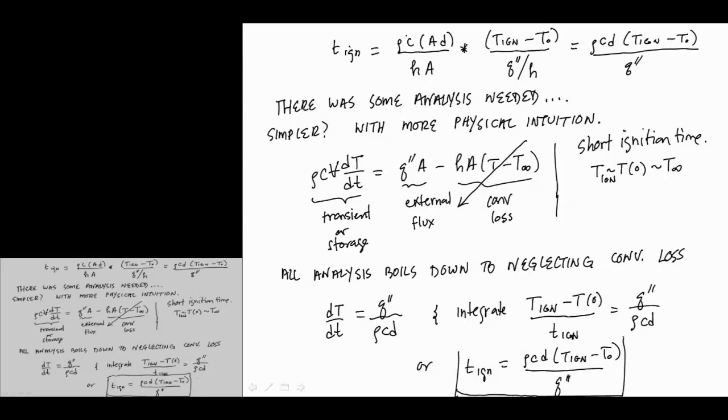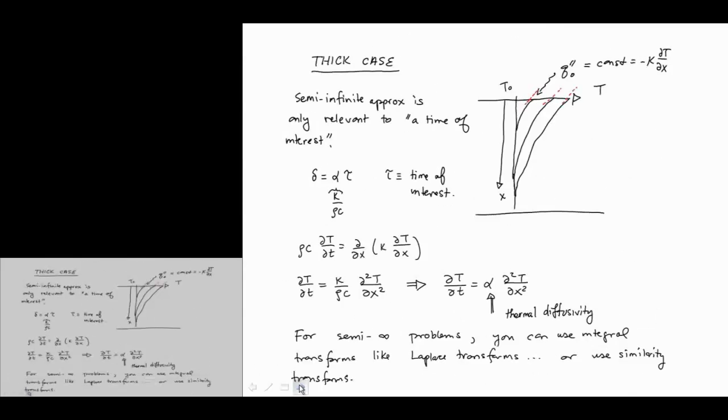Okay, so you'll need to apply this to some simple problems. T_ignition will be given for a range of materials. And we'll go through the process of saying, well, what time will it take for this to ignite, given a specified T_ignition, specified heat flux, a particular thickness, density, and specific heat capacity. Again, there are tabulated parameters. Okay, now for the thick case, this is a much harder mathematical problem. It's a linear differential equation.